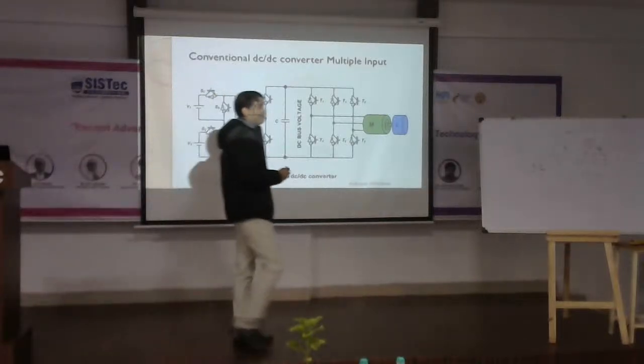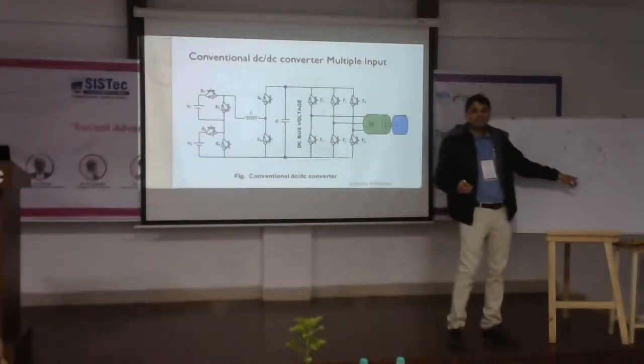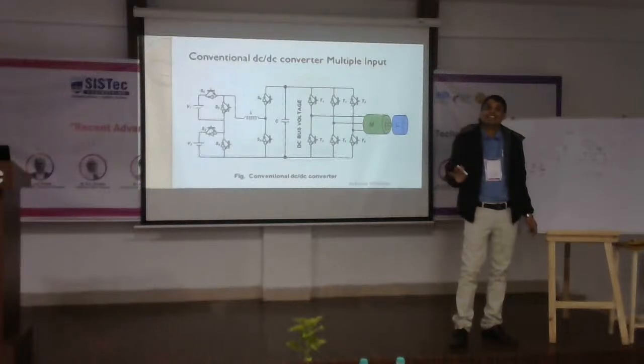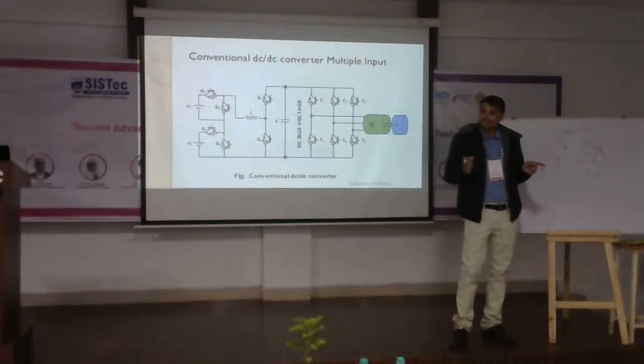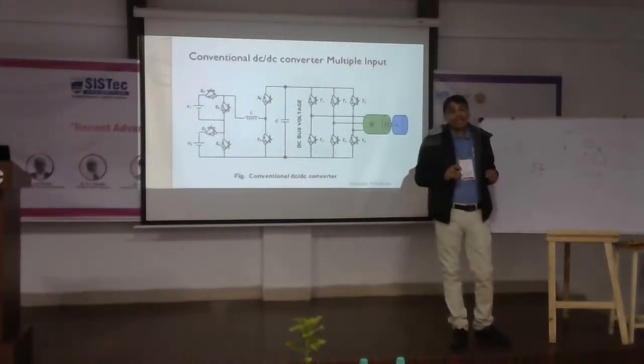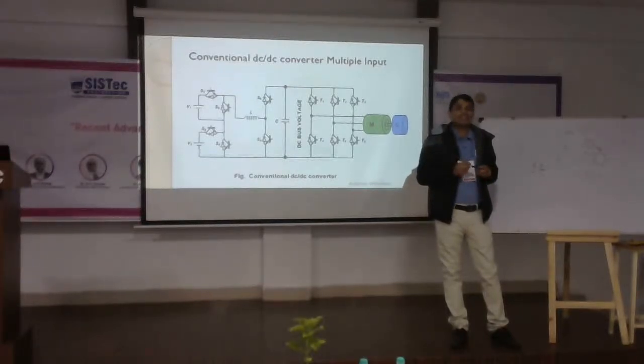Now what happens is, when you provide the variable pulse, it is not as simple as you telling it and it happens. There is an algorithm, there is a logic, that when you press the accelerator, you are required to vary the width of the on time pulse. Getting my point? The same thing will happen here, and that will be done in the digital control, isn't it? Now what is a digital controller? What is the digital control?